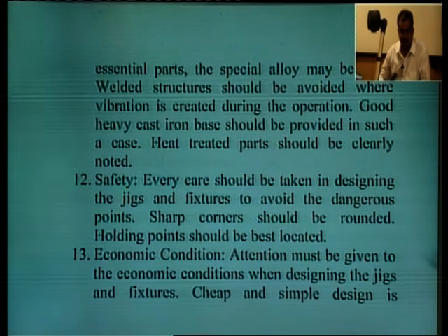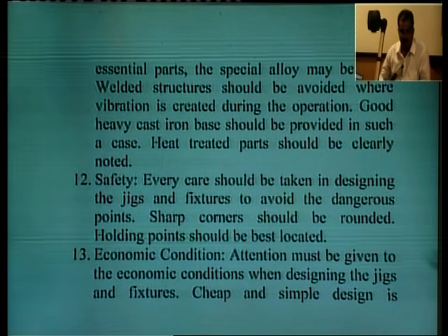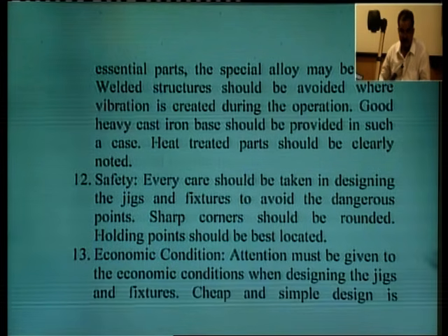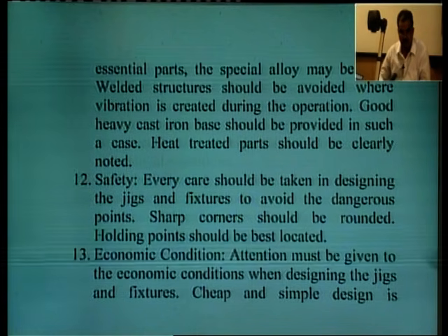Then safety. Every care should be taken in designing the jigs and fixtures to avoid dangerous points. Sharp corners should be rounded off. Holding points should be best located.